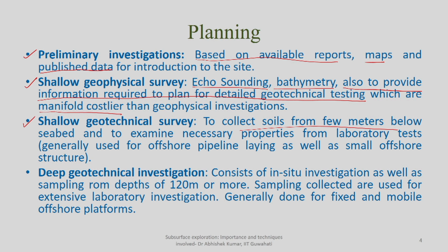load bearing medium. So, in shallow geotechnical survey, you can actually collect the soil sample from those particular depths which are acting as a load bearing stratum, and examine them in terms of properties, in terms of strength characteristics, based on laboratory investigation.